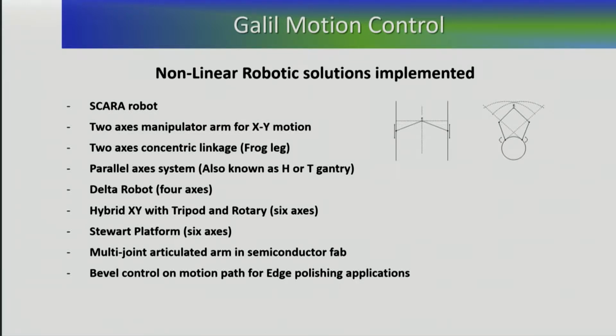Another one that we worked with is concentric robots. So you have 2 circles, and by moving the circle clockwise or counterclockwise on each of the arms, you're able to move the end effector in and out, or if they move in the same direction, you get the theta rotational movement. A combination of the speeds and positions can give you movement within a given radius.